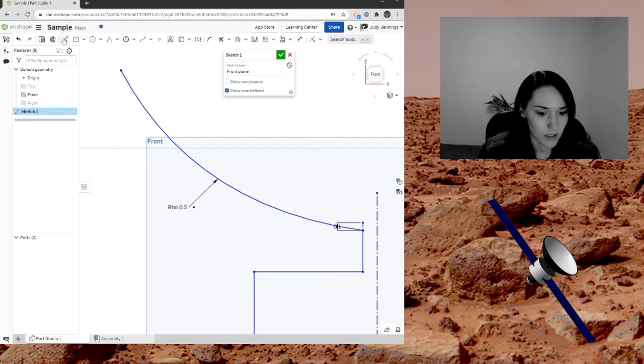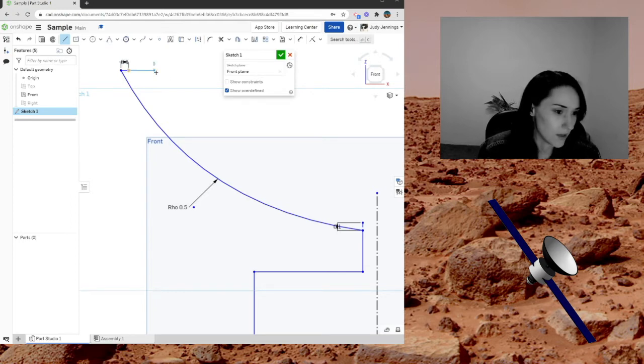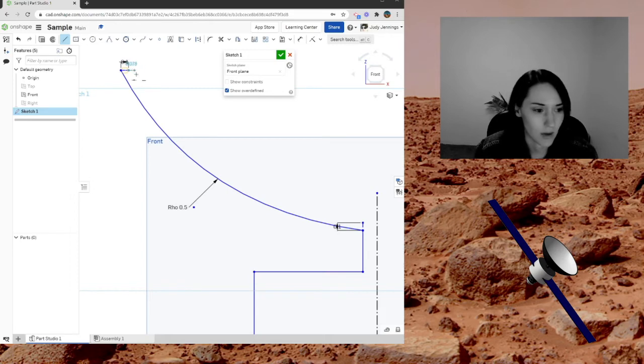Now I'm going to use the line tool again, and create a horizontal line that I want to be the same as the other. I'm not going to spend an hour trying to get it exactly to 0.1. I'll just click wherever. As long as it's horizontal, I'm good. I'm just going to type 0.1, and I go straight to my keyboard. I don't try to click somewhere in the text box. I just start typing. And now I'm going to press escape.